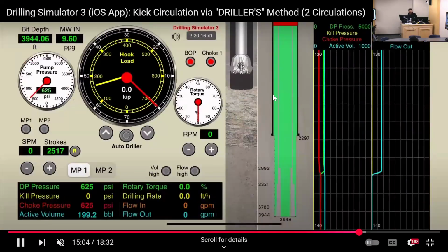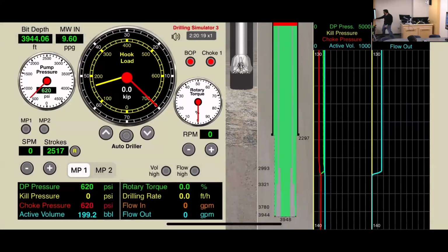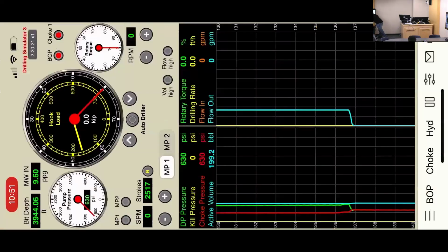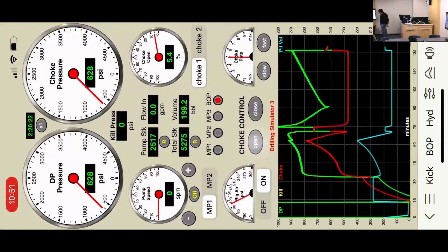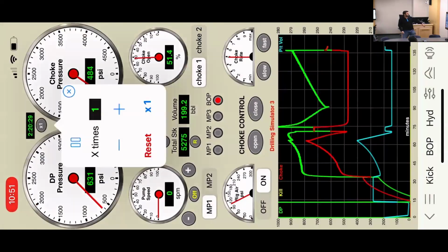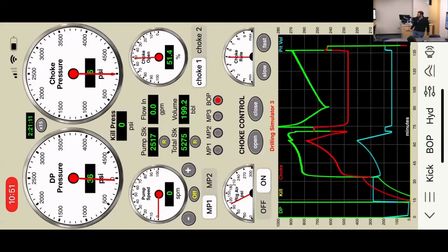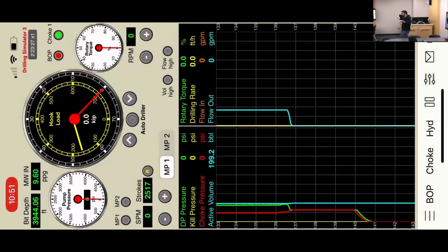Yeah, I mean, okay. I sped it up, and this 600 PSIs, whatever, it will eventually become 0. Okay, and to show you guys, I'm opening the choke to half point as it was before, and I speed it up. You see, it goes to 0 very quickly, well, not that quickly, but you see 0, 0. I know I'm good. I know I killed the well.